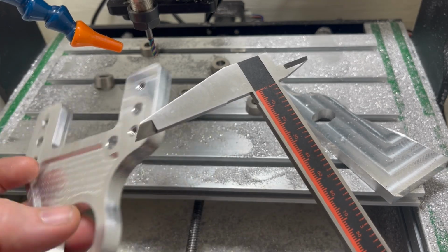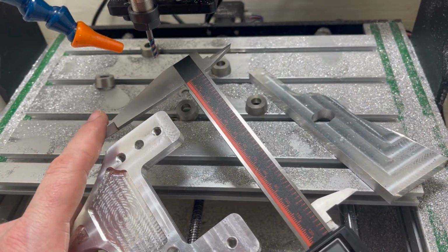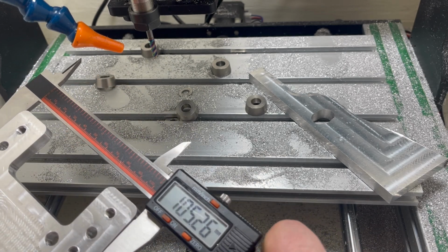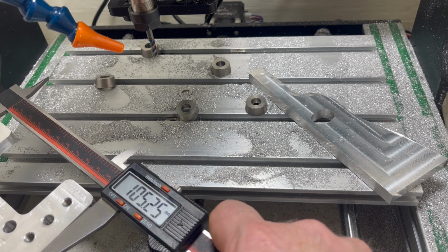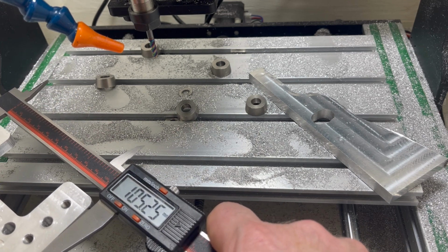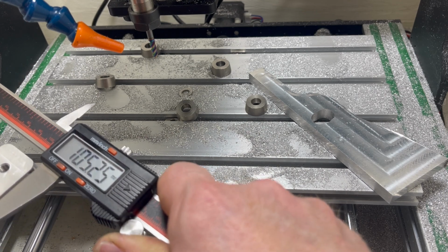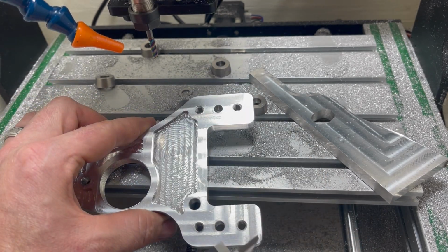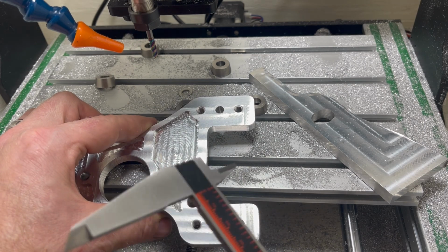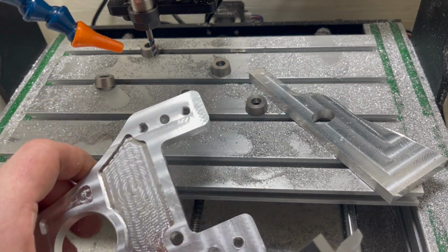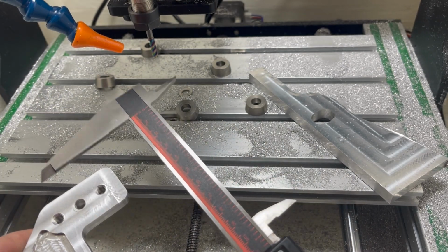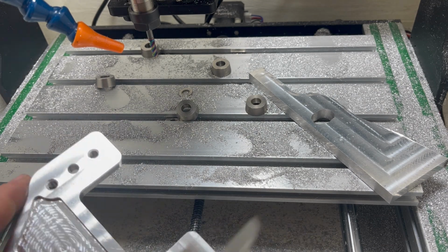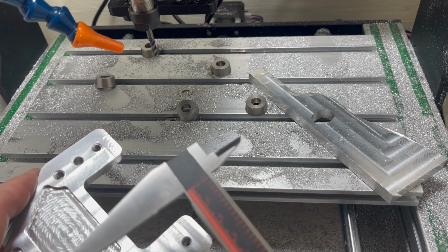All right, now we can take our part that we just made in here and just see what it turned out to be. This is supposed to be 105 millimeters even. And as you can see, I got a 1/4 millimeter greater than what it should be. It's really close, over 100 millimeters. And obviously the longer the distance that it's measuring or traveling, the greater the error. But it's really close, and I don't want to go through this process again and do all the measurements. I'm just going to use this data that I just collected here, maybe just trim off that last decimal place to a greater number or a lesser number. In this case, it would be lesser.